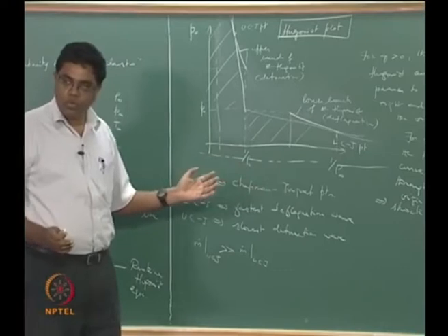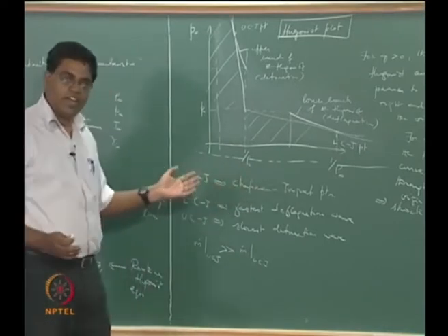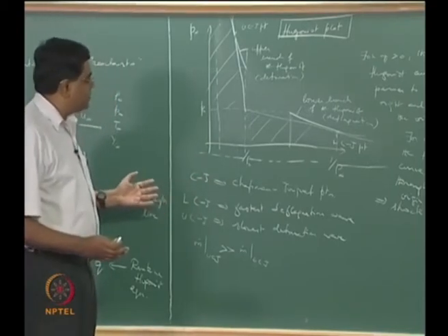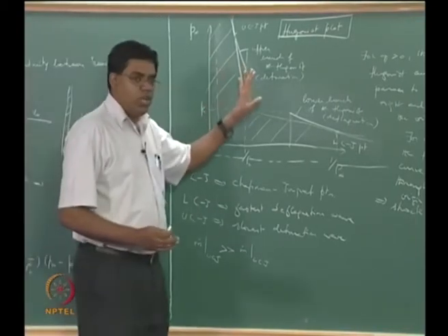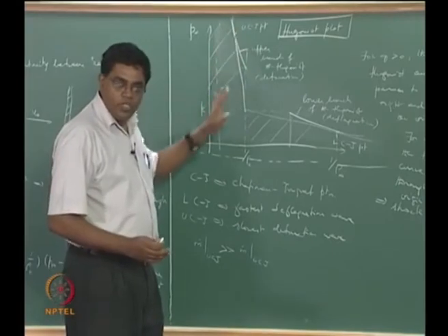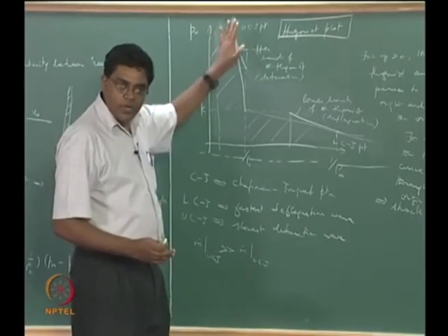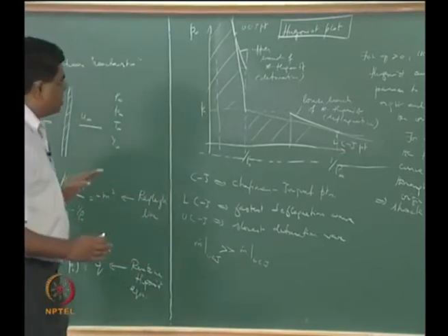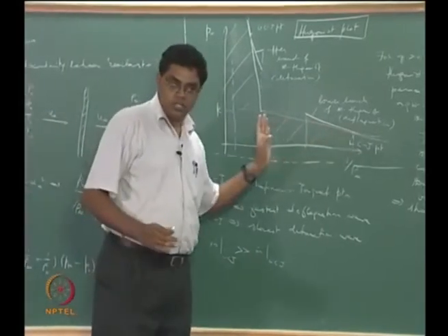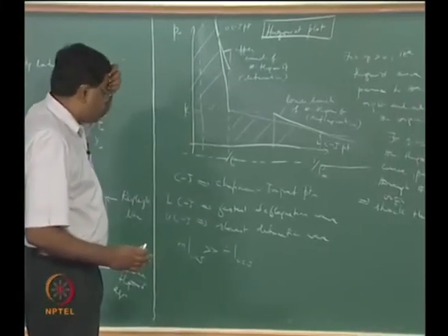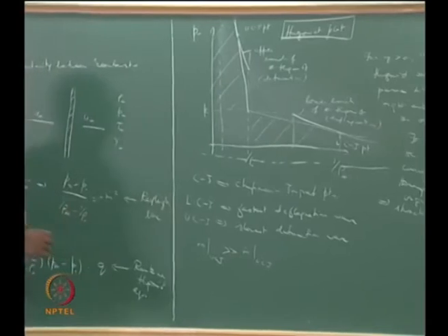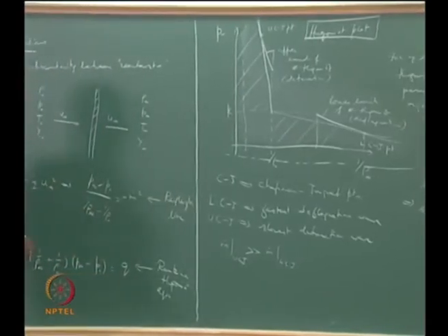What we went through in gas dynamics is basically a non-reactive case as opposed to a reactive case here, and the moment you have reactions, then it belongs to only one part, which is like the supersonic propagation, as we will see and show, corresponding to detonation, whereas there is also another part corresponding to deflagration, that is subsonic propagation, where expansion happens rather than compression.